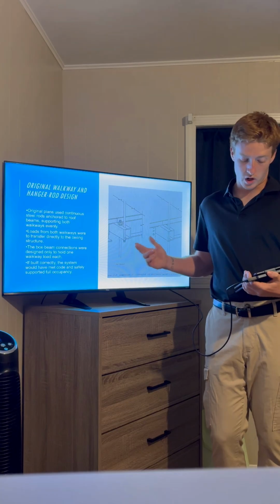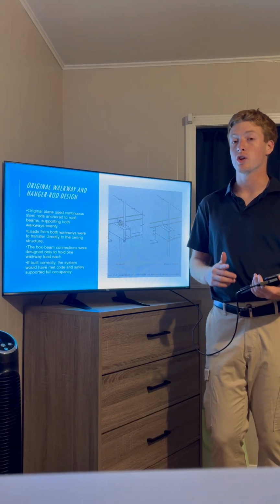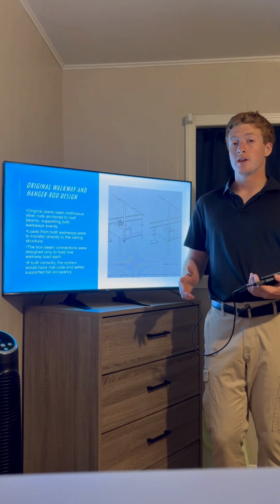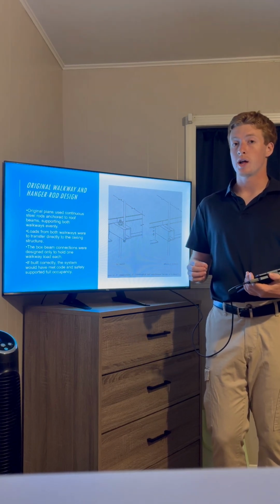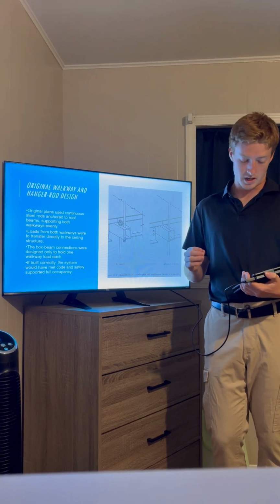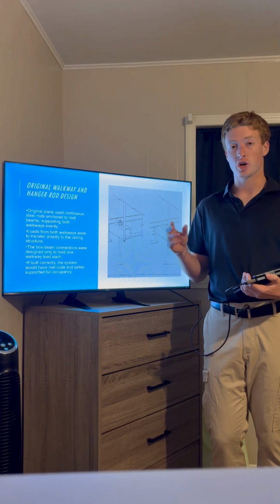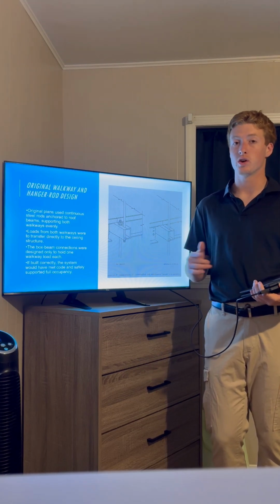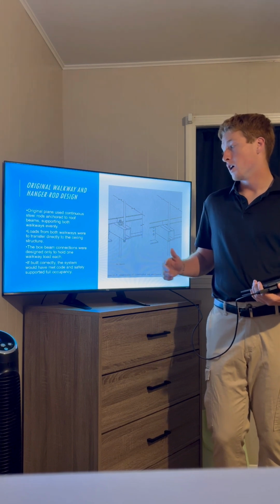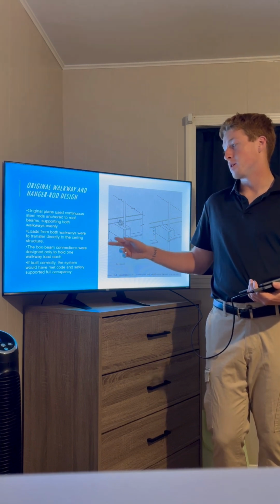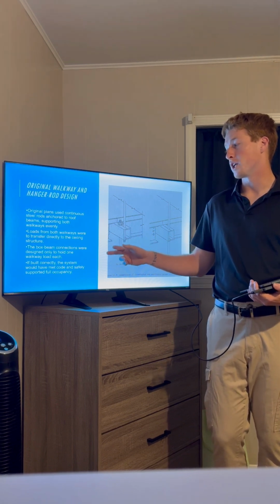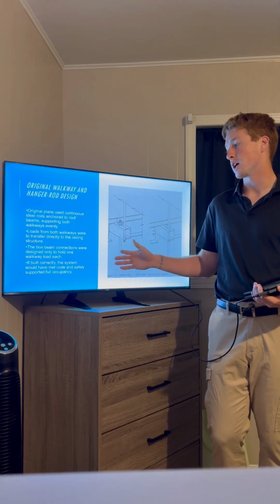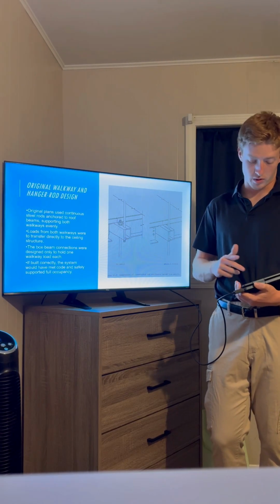The walkways were hung from the ceiling by long steel rods called hanger rods. In the original design, there was supposed to be one continuous rod that ran from the ceiling to the walkways, so each carried their own weight directly to the ceiling, which is called a proper load path. But the box beam connections were designed only to hold one walkway load each. If this were to be built correctly, the system would have met code and safely supported the full occupancy.